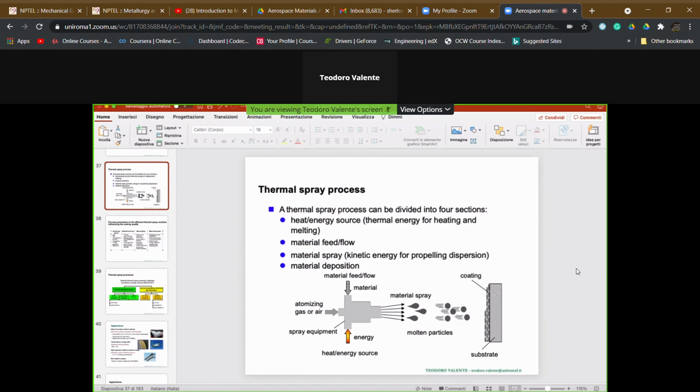For the material spray, that is the part of the process in which the gases interact with the particles before the fabrication and realization of the coating, we have to know, and it can be modeled using the most advanced fluid dynamic approach, numerical I mean, the gas exit velocity and the gas velocity distribution, the temperature distribution of the gas.